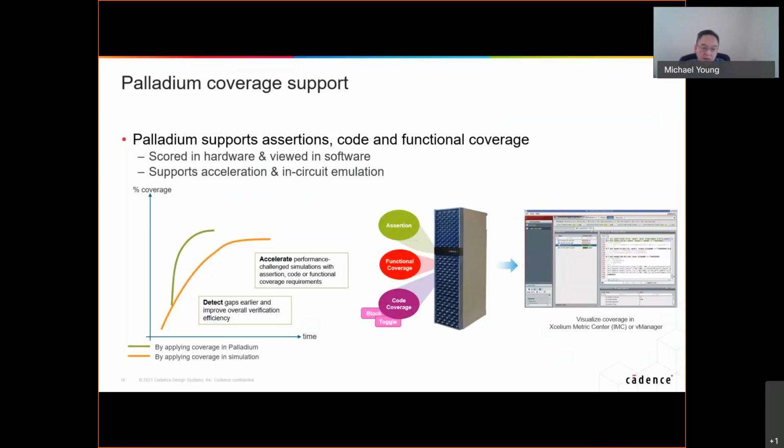And not only that, if you have Xcelium, you can also merge the coverage that you have with the result from Palladium. So now you get a much broader coverage model than what you would get running by itself. And all this capability can be visualized either in our IMC or vManager. So this is all the goodness in providing that level of intelligence.